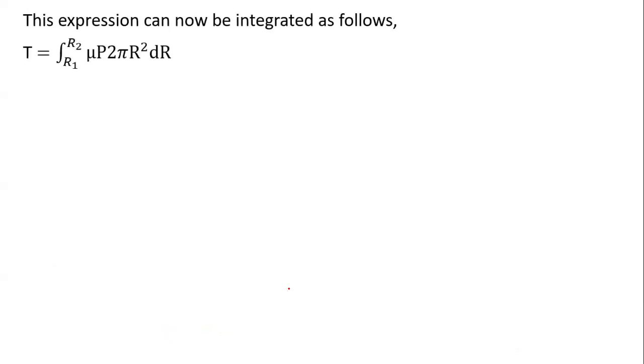Now what do we do? Why don't we go right ahead and integrate this expression? Integrating this expression between the limits R2 and R1 means that we're now getting not just the torque on the elemental area, but the whole clutch, the whole plate clutch.